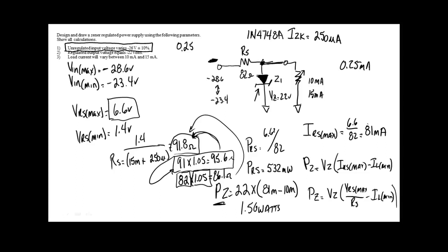What you're going to run. What's this regulated power supply got to run? And then that would set what? That would set everything. That would set your transformer, right? That would set everything down the line. Of course, with these guys you can't do very much because they're not designed to handle a lot of current. 15 and 10 milliamps is not much of a load. It'll run an LED, great.